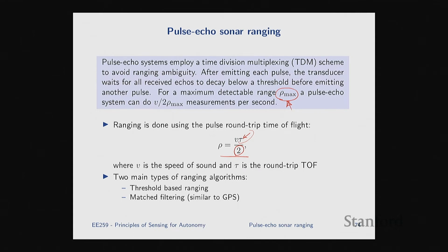And that's exactly true. It does happen, and that's why you're never perfect. Some of your range measurements are completely wrong, and this is one of the effects that can introduce that kind of error. You always can have a very strong reflector. It's not the biggest factor, as we'll see. There are things that are much, much worse than this. But every now and then, yes, you can get something at a range higher than the max range you assumed when designing your system and algorithms, and that could give you a false positive detection.